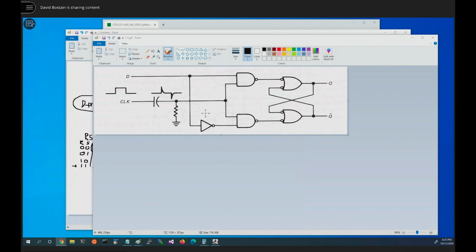So we're guaranteed that these are always opposite, which is exactly what we want, because if you recognize this, it is simply a latch, and the latch has a clock in front of it, and the clock itself is triggered by R and S. I may have them backwards with the labeling of the chip, but let's pretend that's reset and that's set.